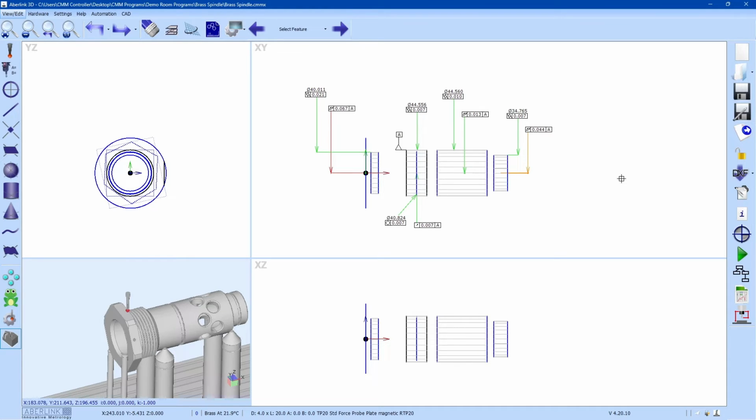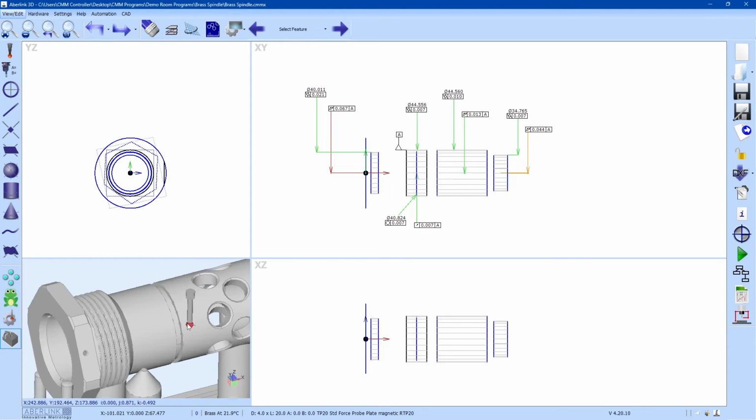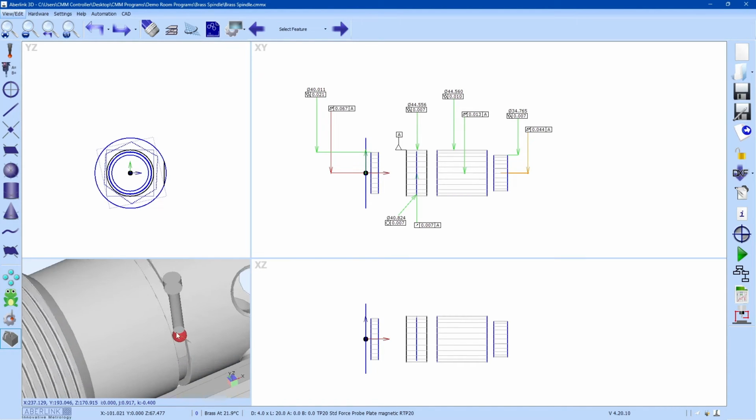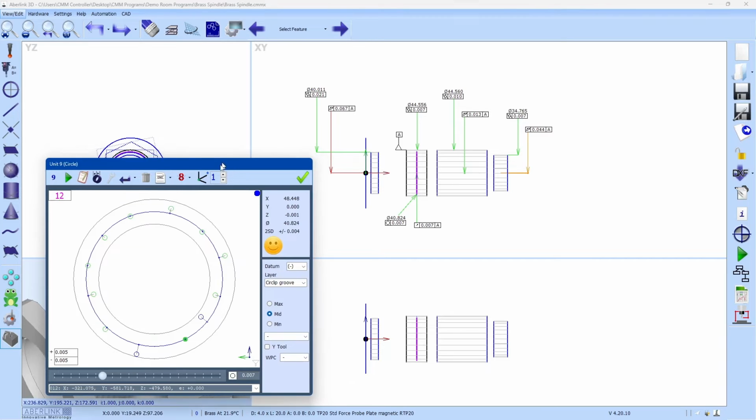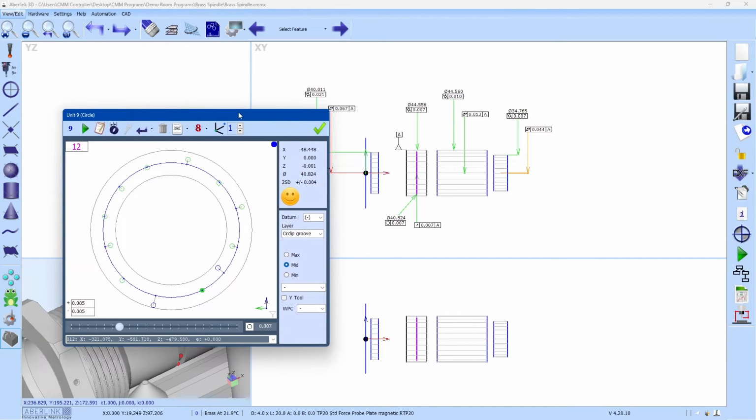So this just shows the nominal setup. However, you can actually highlight the setup that I'm about to cover with the circlip groove or the O-ring groove. So that's that there. These are typically very difficult to measure as cylinders, and this is where we have to utilize the circle projection into the datum feature itself, just to align the dimension correctly. So we do measure this as a circle. This is the circle here. I'm going to show you some measurement tips later on how to actually measure the full diameter, even though the part is on its side.